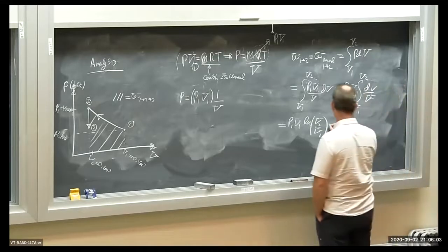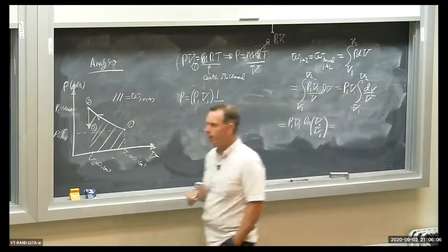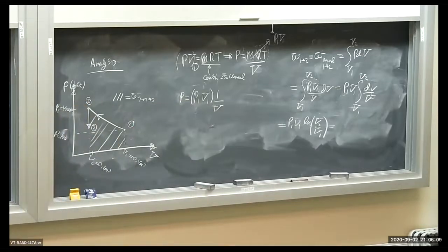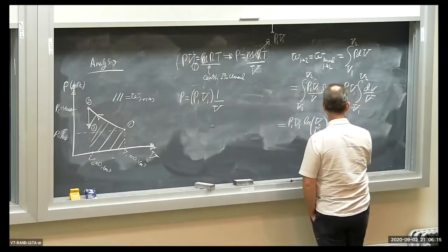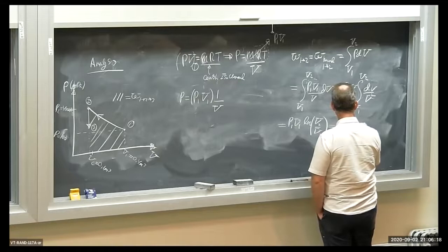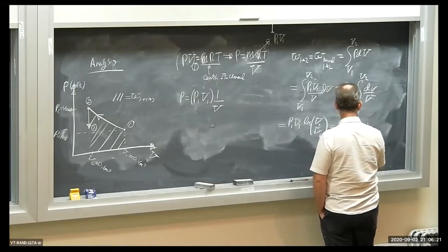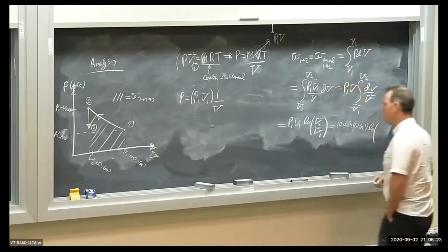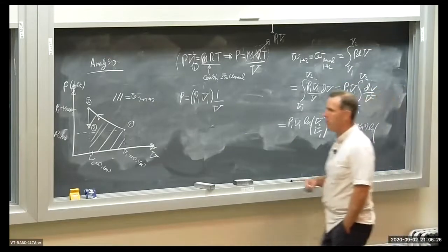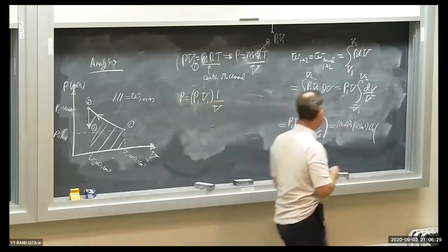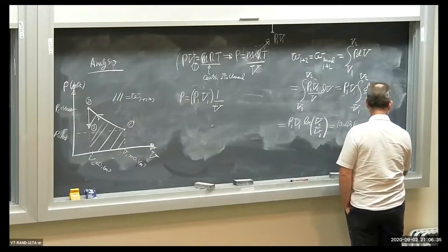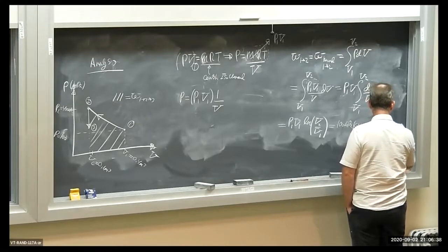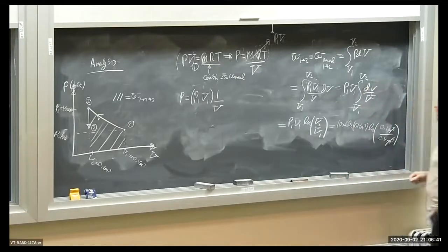I know everything. I know these volumes, and I know pressure P1. The pressure was 100 kPa at state 1. The volume was 0.4. So I have 100 kPa, 0.4 cubic meters, and then the natural log of V2 over V1. V2 was 0.1 cubic meters, and V1 was 0.4 cubic meters. The cubic meters cancel out in the natural log. It better be dimensionless in there. Okay?